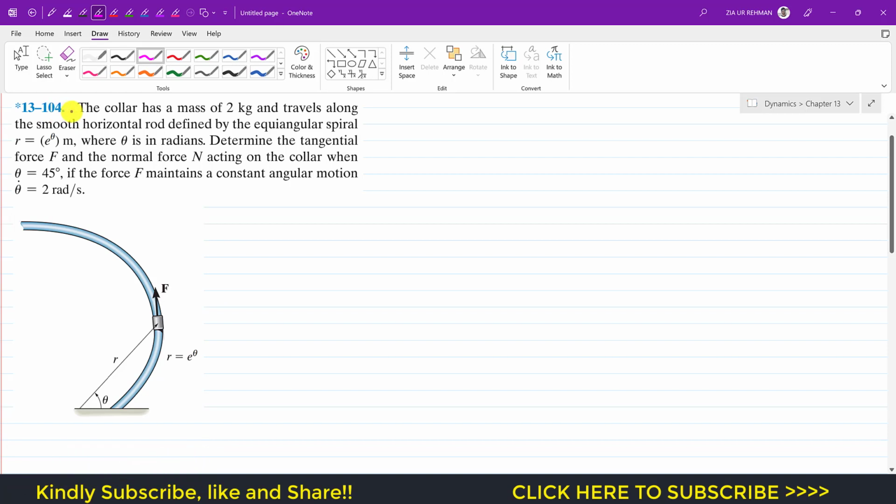Now we are going to solve this problem from chapter 13. The problem says that the collar has a mass of 2 kg and travels along the smooth horizontal rod defined by the equiangular spiral r equals e to the power theta m, where theta is in radians. It is said that determine the tangential force F and the normal force N acting on the collar when theta equals 45 degrees, if the force F maintains a constant angular motion of theta dot equals 2 radians per second.